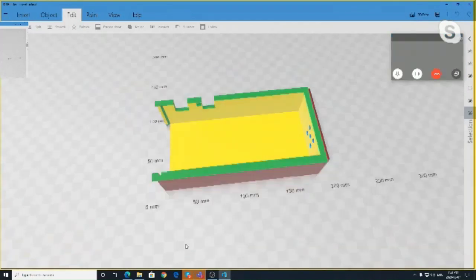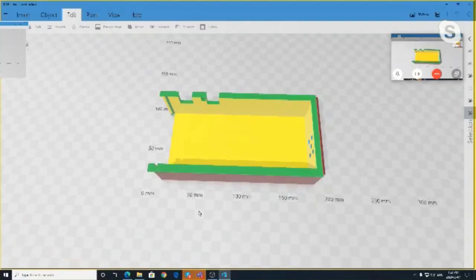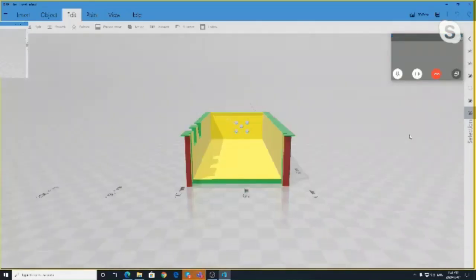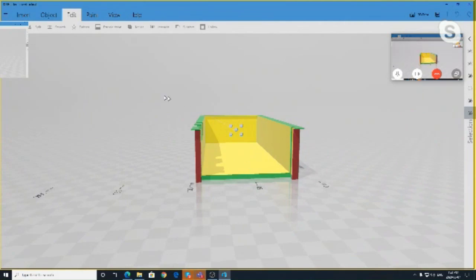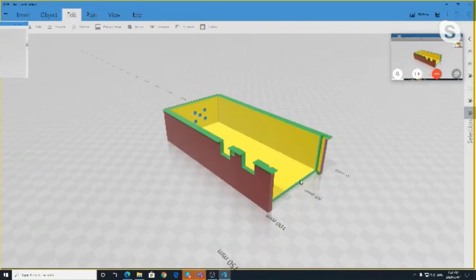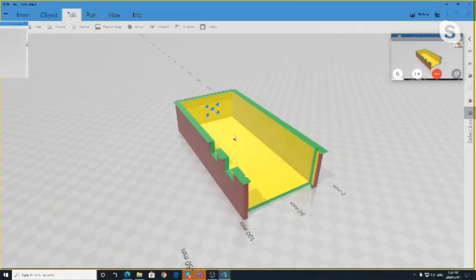It's a cover for an Arduino. I found online an Arduino bracket that my Arduino slides into, and I wanted to cover it to keep it from dust. So I designed this cover, and I used a lot of subtractions in order to hollow the object out and to make the grooves so I can actually slide. I've got another slide that goes in here that attaches a small fan to it that blows the air through and keeps everything nice and cool.